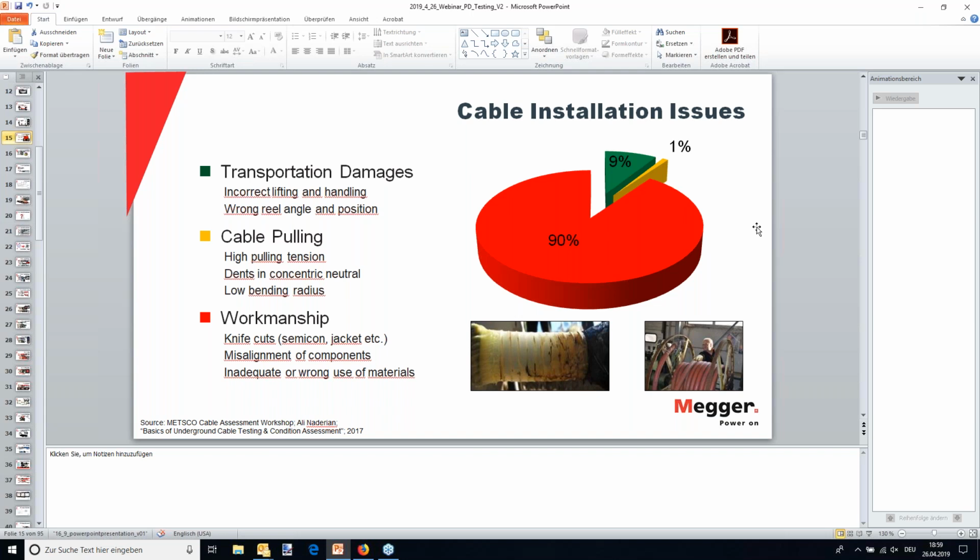On service-aged cables, just monitor it. Once you get activity at 1.7 and then 1.5, 1.3, keep measuring every so often. And again, accelerate based also on the importance of the feeder. An unimportant cable does not have to be tested as often as an important cable. And even an uncritical important cable should be tested much more often than maybe a medium critical cable that is not so important. Again, you want to maximize the time of the asset and find the sweet spot when to go in with your money and work some miracles.